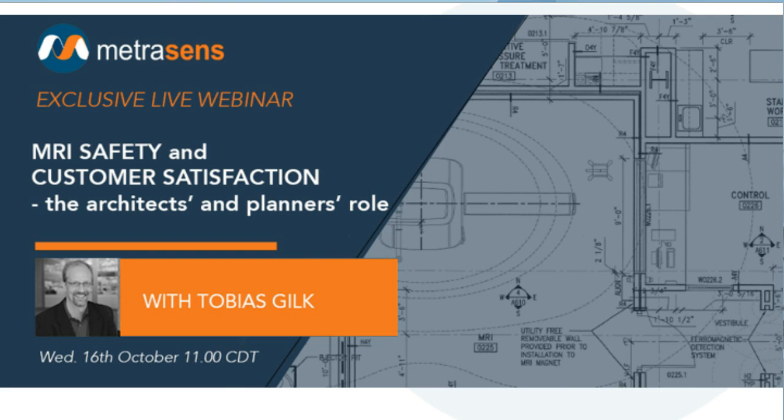Those changes mean that the outward swinging door, if the magnet quenches and the room pressurizes, a latching, airtight sealed door is not going to be pushed open by the positive pressure building up inside the room, which means that even if the door swings in the outward direction, it's not providing the safety benefit that we thought it was. So the contemporary design standards say put in an overpressure relief mechanism to allow that pressure to escape